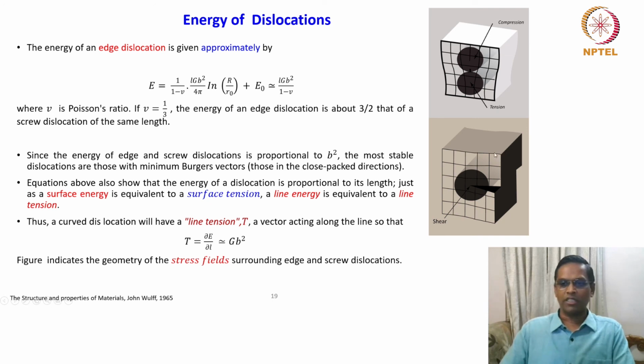So this is a stress field behind these two dislocations. Again, when you talk about stress, so far we have just seen the energy of dislocations. Now we are going to move on to stress fields, which is again very interesting, and you will be very happy to see that most of the expressions you are already familiar with, right? Because they are all treated by elasticity theory.